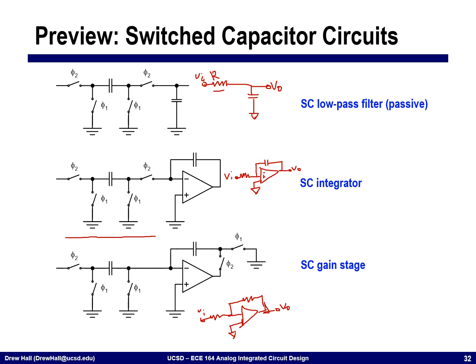And so now I've built an amplifier that, by combining phi1 and this switch, during phi1, we essentially connect this capacitor to ground, depleting all the charge. So we set Q equal to 0. At the same time, we're also disconnecting this capacitor. This other side is set equal to 0. And so both sides of this capacitor are also shorted.